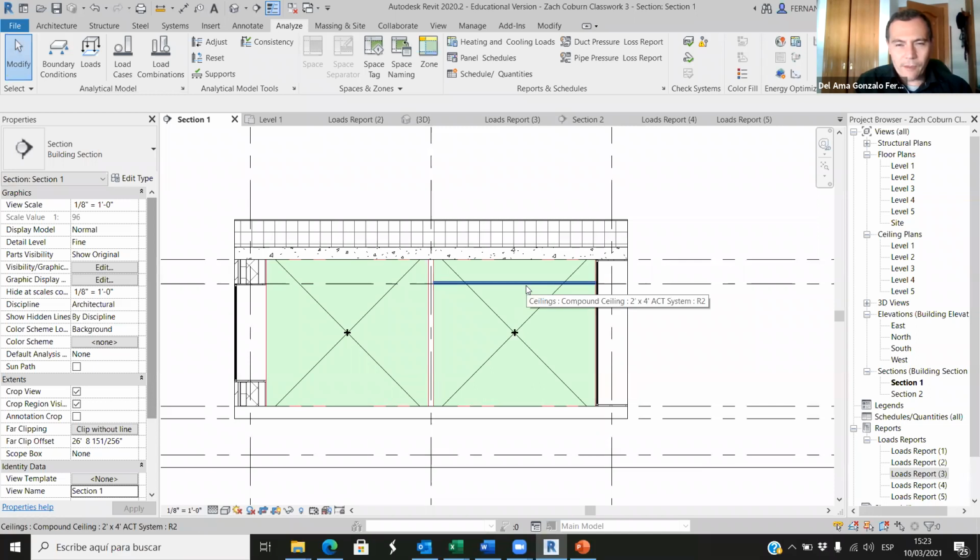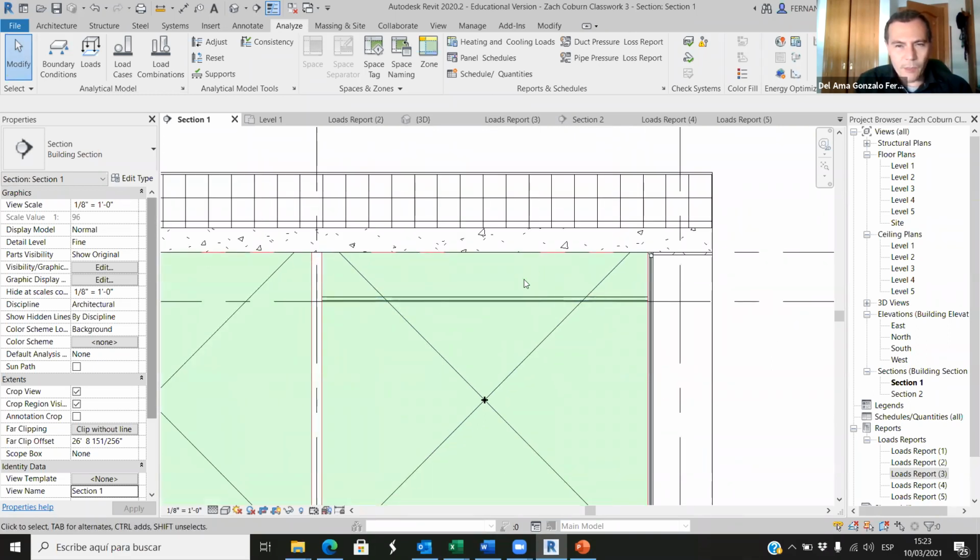If you didn't have a false ceiling and you just create that space, by default, you create that space from the floor to the roof. Okay, that's fine. If you create a false ceiling, you can do that, and you can do this in terms of design because you want to hide the equipment or the mechanical systems we have here. But then you have to make sure that this is not the room boundary. And if it is the room boundary, we have to create another space here in the false ceiling, which is too much work.